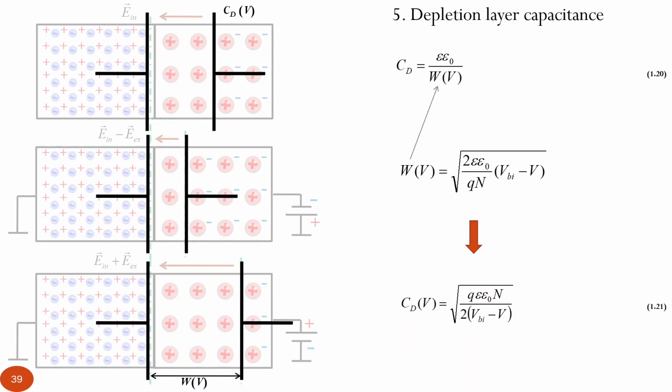As you see from here, that's important to underline. We will discuss this in detail, of course, the rectifying properties, like JV characteristics of a PN junction. But besides the fact that a PN junction, and a diode based on it as a device, is applied to rectify electrical current, so it possesses different conductivities at different polarities, it also can be applied as a variable capacitor.